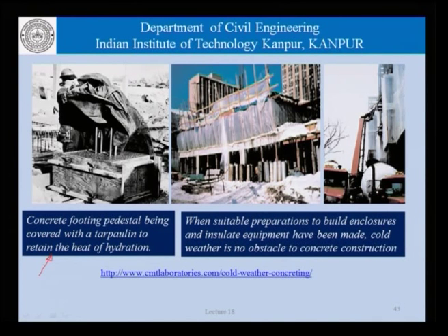So, if this concrete is just allowed to dry or allowed to be exposed to the atmosphere, which could be very cold, the strength development is highly retarded. We can address that issue by covering it appropriately with a tarpaulin. Similarly, as far as the picture on the right is concerned, we need to carry out extensive preparation to build enclosures and insulate equipment in order to ensure that construction in cold weather can be carried out unimpeded.